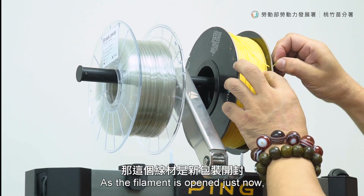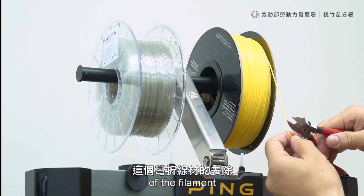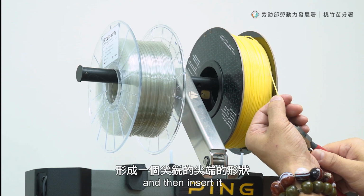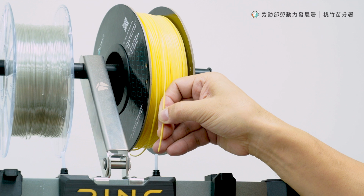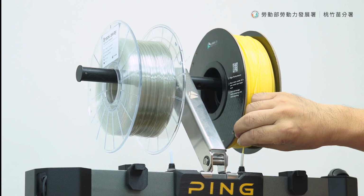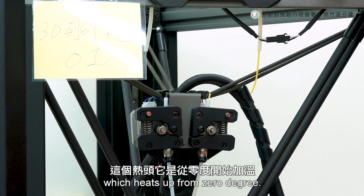The filament is open just now. The packager bent the end and hooked it onto the holes. Pulling it out, we need to trim the hooked end of the filament with a model cutter. Cut it at an angle to create a sharp tip. And then insert it into the first white tube for output. Next, we see the second white tube leads the filament into the nozzle, which heats up from 0 degrees.